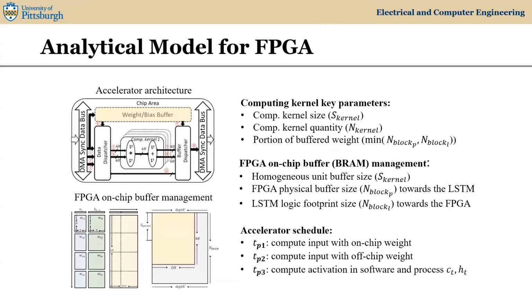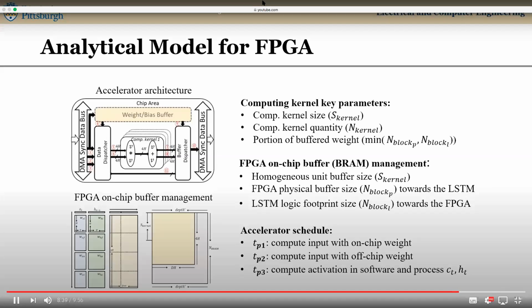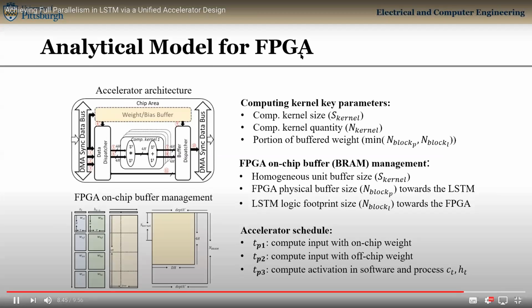We also built an analytical model to mitigate the gap between the accelerator design and the hardware features, such as DSPs and the block RAMs on FPGA. With the given FPGA and LSTM, the analytical model can determine, first, the computing kernel key parameters such as kernel size, the number of kernels, and the portion of weight that can be buffered on the chip. Number 2, device buffer management, such as the unit buffer size, the FPGA physical buffer size, and LSTM weight footprint size. Number 3, the running schedule of the accelerator.